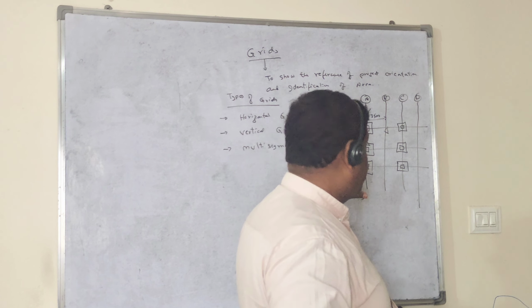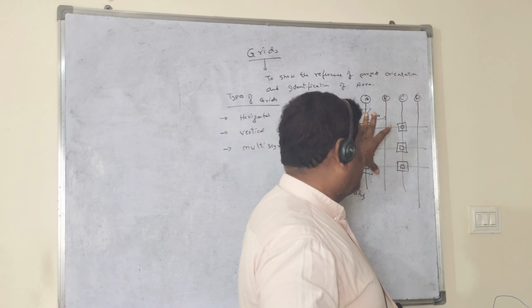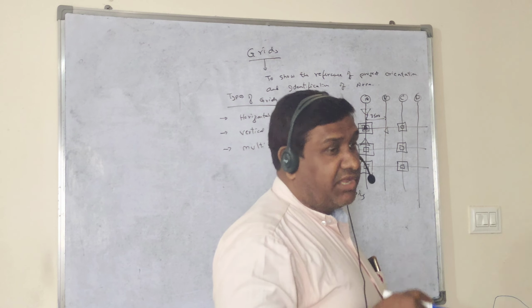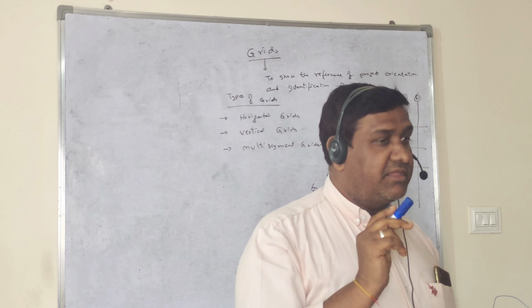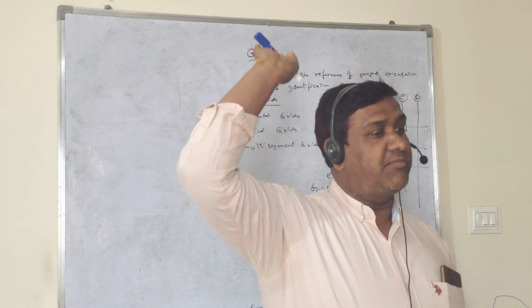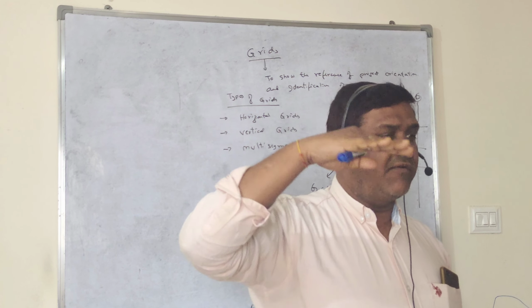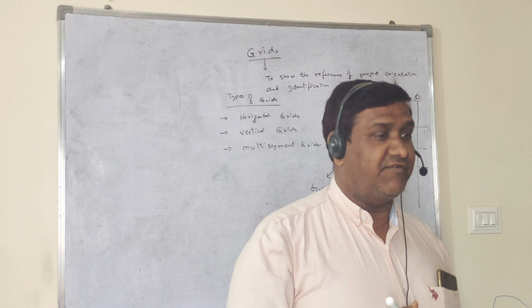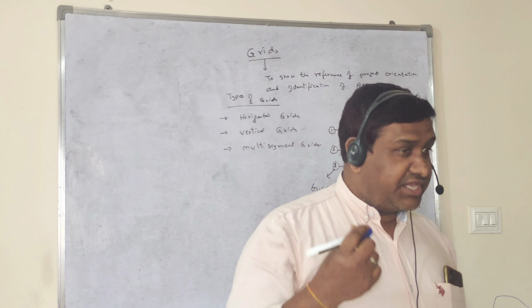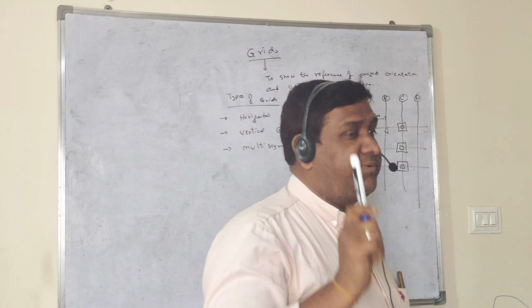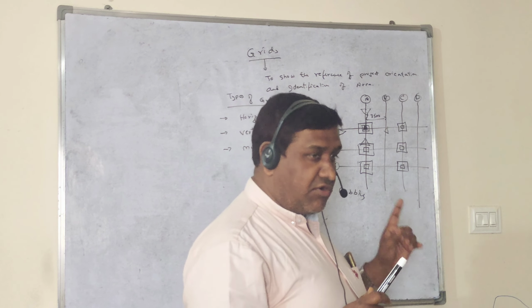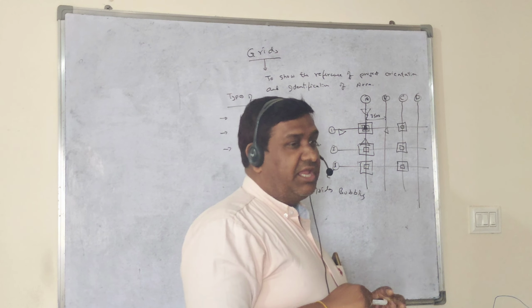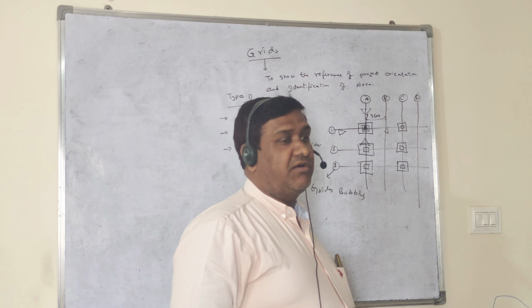So always remember, this grid is going to be placed in the project. If you place one grid in one floor plan, it will be reflected in all floor plans. There is no need to place the grids again on all the floors; it is not required in Revit. So these grids we have to place in the site plan or zero level. Wherever the zero level or ground level is, at that level only you have to place these grids, vertically